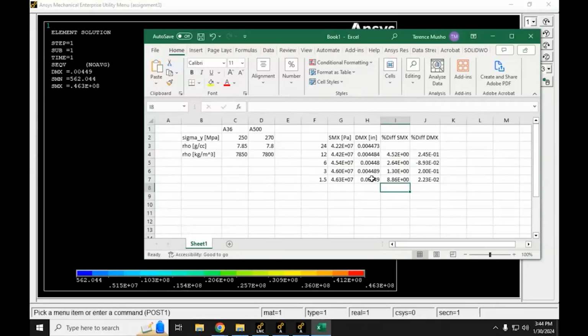Anybody who's an aerospace engineer is dealing with very tight safety factors. You could be under-predicting your stresses by 8% if you don't do a mesh independence study, which could be considerable. So it's always important to do mesh independence when you're running finite element simulations, if you can. Sometimes when you have extremely large models, you can't actually do this type of study, in which case you just have to have confidence in your finite element model results. But typically for most models you want to do this.